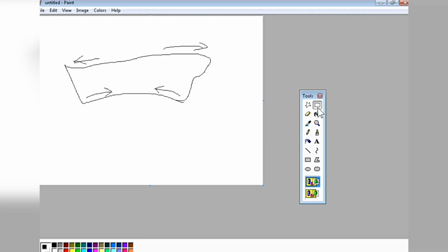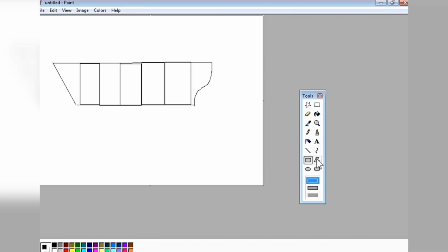Now, where is the shearing stress coming up? When you're loading your vessel. Now, this is a vessel. You're loading full here, half here, full here. Now, you have two forces coming up here. The gravitational force is pulling down, and here you have a buoyancy force which is pushing it up, because the buoyancy here will be more than the force of gravity. Here the gravity is more than buoyancy, it's pushing down. And here the buoyant force is more than gravity, so it's pushing up.